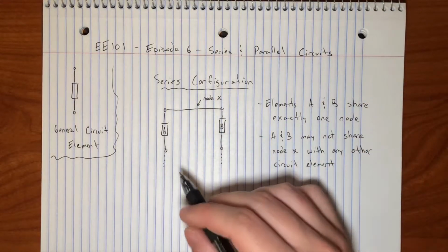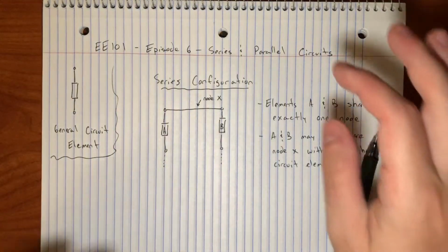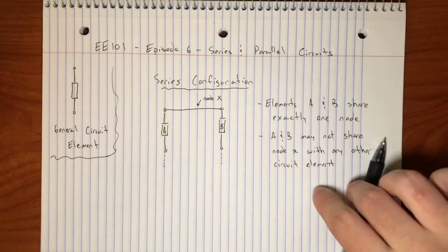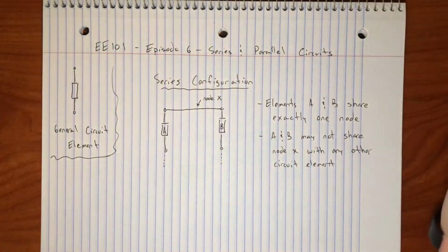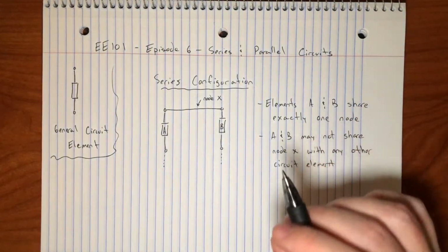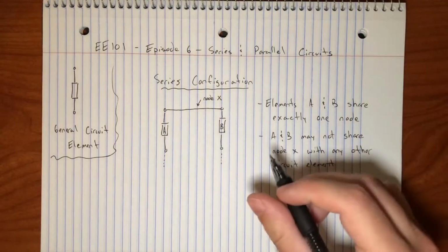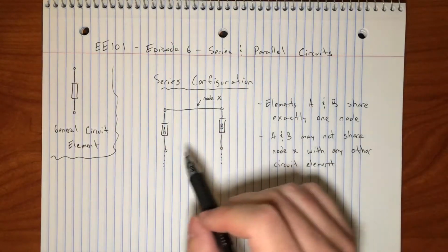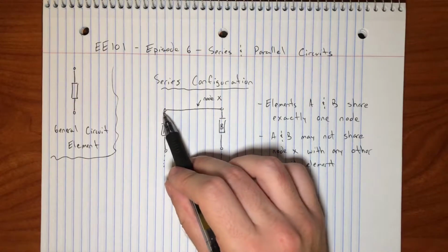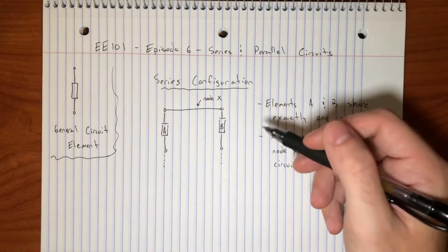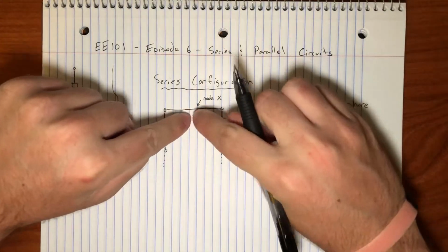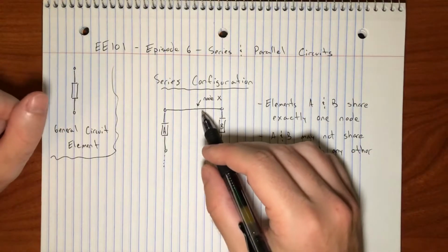It really is as simple as it looks. It's just two circuit elements cascaded. They're going end to end. One leads into the other. But just to tie up any potential loose ends here, this is the strictest, while still remaining general, rule you can concoct here. So all it means is that A and B are only connected together in one place on one side, and it doesn't matter which side, as long as only one side of A and one side of B are connected together at this node, and no other circuit elements hang off this node.